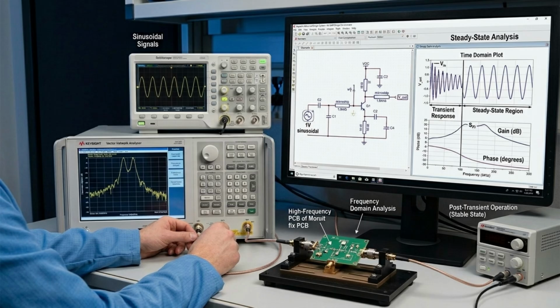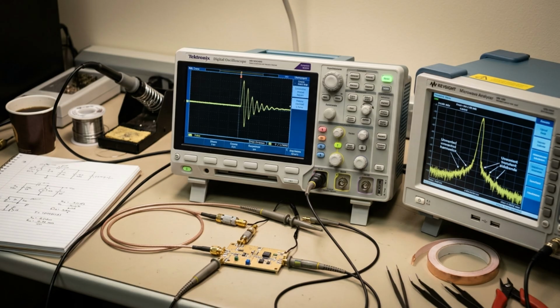In RF engineering, steady-state analysis is commonly used to study sinusoidal signals in the frequency domain, where systems are assumed to operate after all transient effects have settled. This simplifies analysis of gain, phase, and impedance. However, transient effects still matter in RF systems during switching, modulation, and signal startup. These short-term behaviors can affect spectral purity, introduce distortion, or create unwanted harmonics.